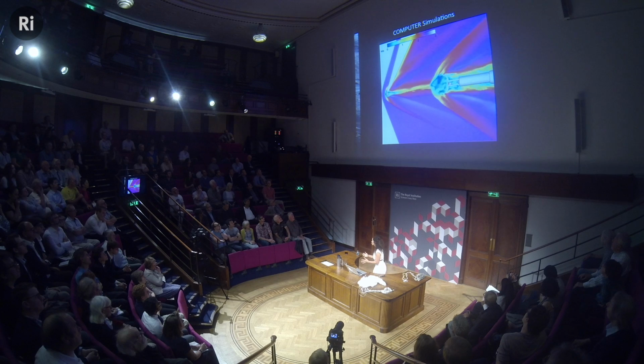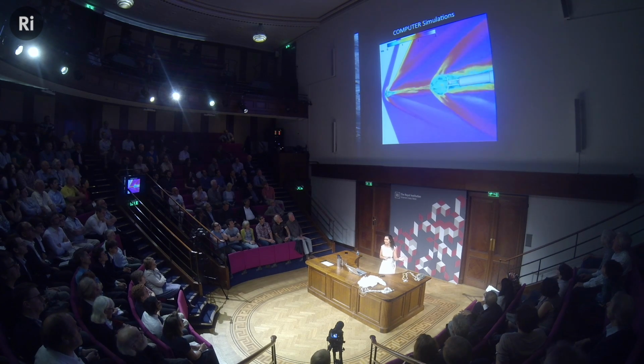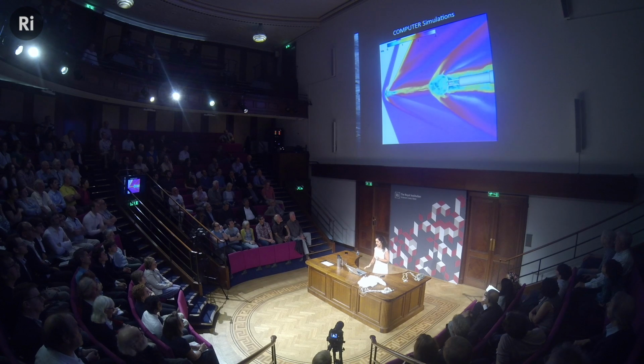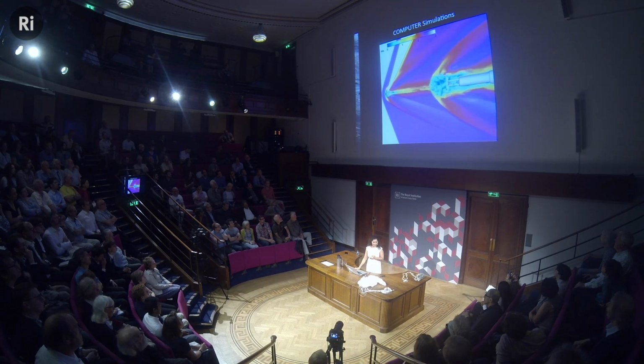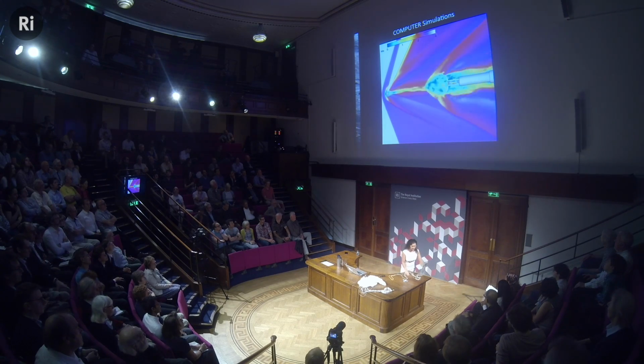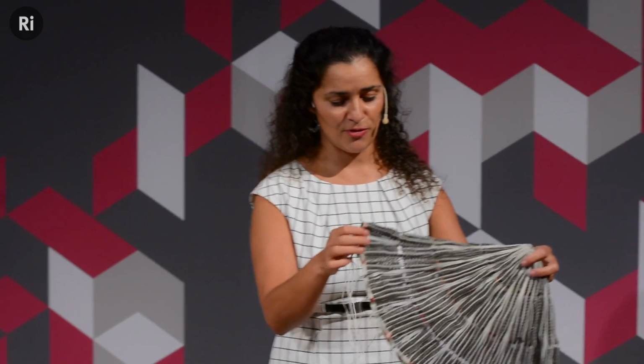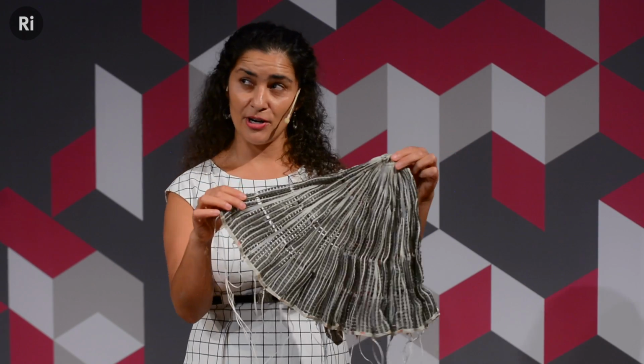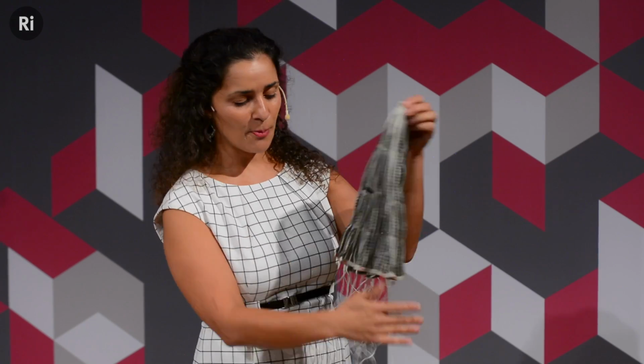But when you do a computer simulation, the simulation is only as good as it is correct, right? Just doing a simulation isn't enough. You have to validate your simulation. What we did to validate the simulation was build little subscale parachutes. We've got one demo coming up, but I'll show you an example of a subscale parachute. This is something we developed for the human space program, but you can get an idea that this size parachute is roughly 3% of the size of the full-scale parachute. So if you build an identical model in terms of geometric shape, you should get similar aerodynamic performance.